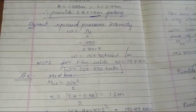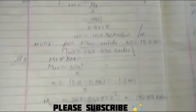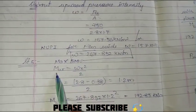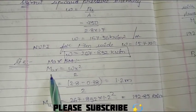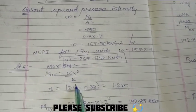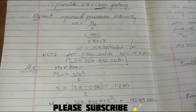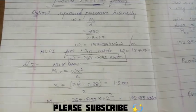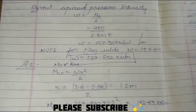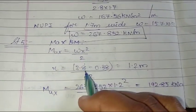First of all, we have to do this. Next, we are calculating the bending moment. Here the bending moment formula along the x direction we are taking as Wx square by 2. Along the x direction, that is why we are taking x square. If it is along the y direction, you will be taking y square. Maximum bending moment is going to be Wx square by 2.